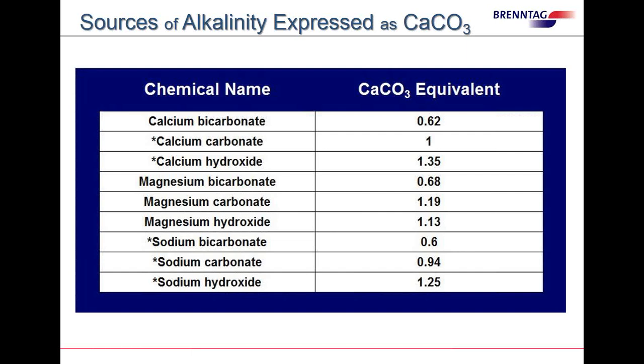Now, keep in mind one cool factor on sodium bicarbonate, which, if you're not sure about what that is, comes under the name of Arm & Hammer in the store, and it's baking soda. Nitrifying bacteria, or the bugs that eat nitrogen, eat sodium bicarbonate, and that's basically the only thing they do eat. So this has to be in the water in order to make it work. So sodium bicarbonate's always a good choice.